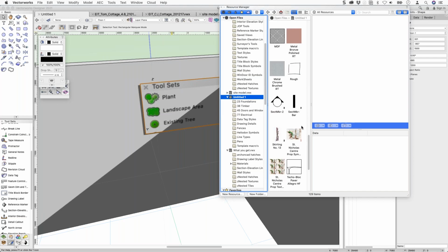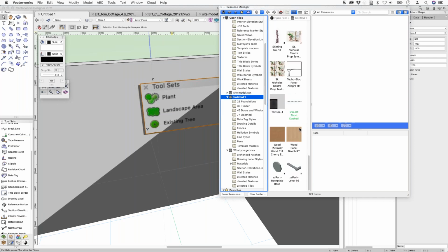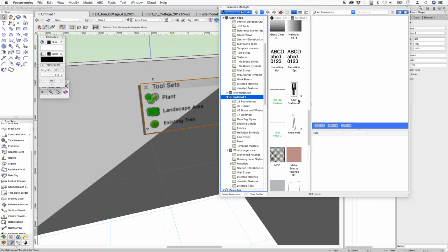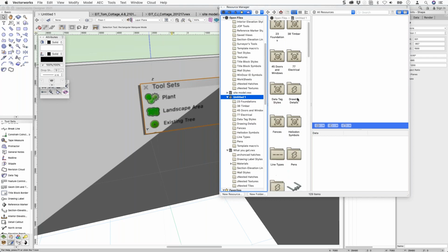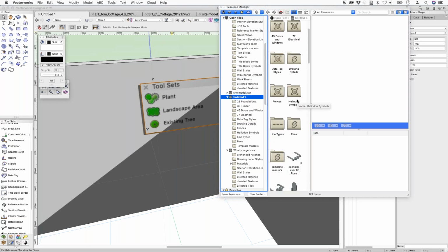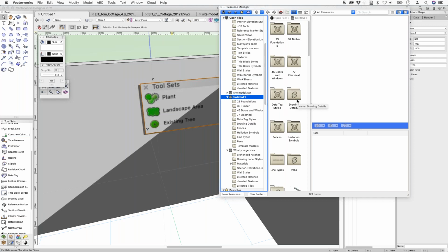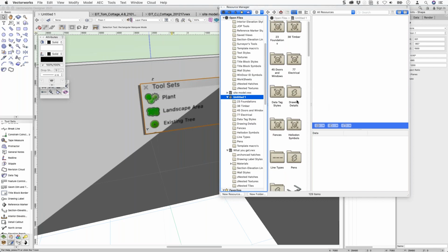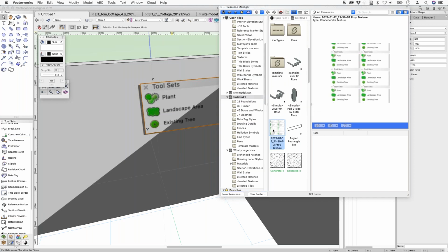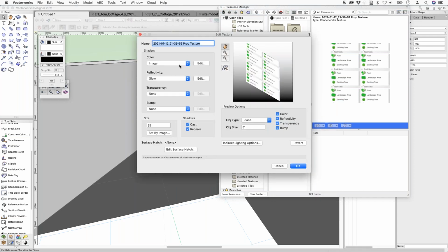And the texture should be called something like, not St. Nicholas, should be a number. Timber. There it is. That's my texture. Let's edit the texture. So it's an image. It's got glow reflectivity. So watch out for that because that can stop it. Let's turn off, none. Let's have no reflectivity. Okay.